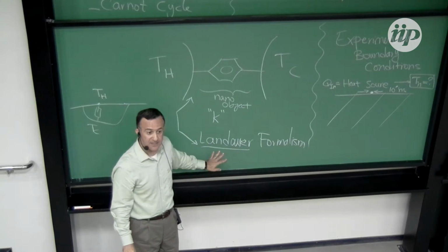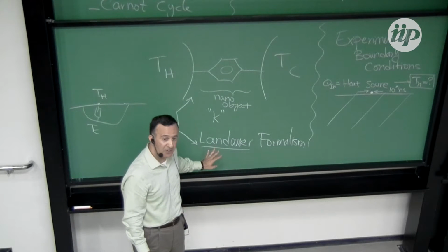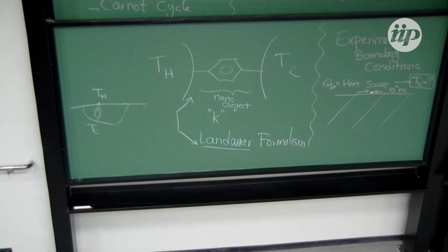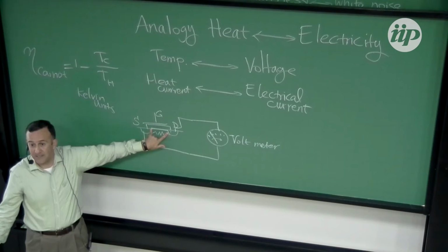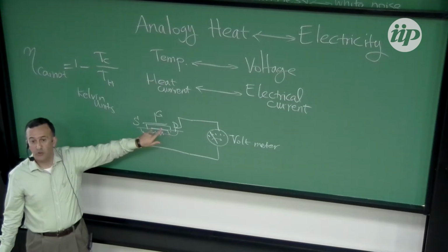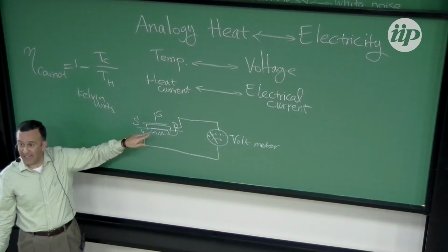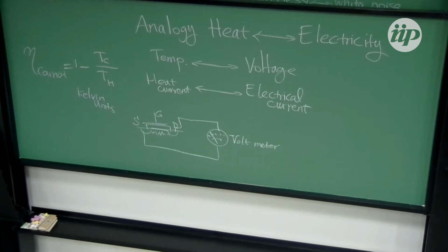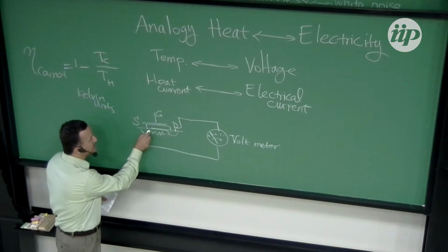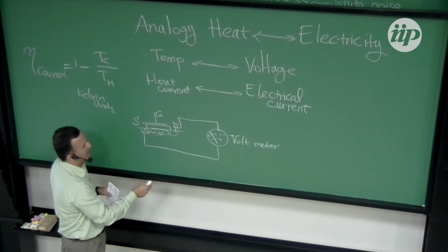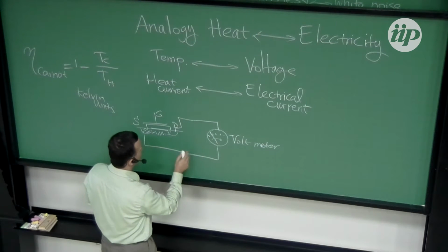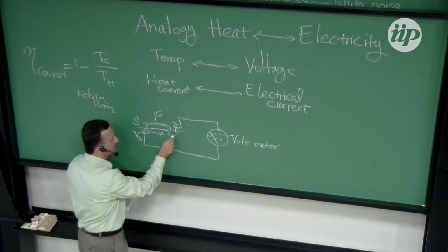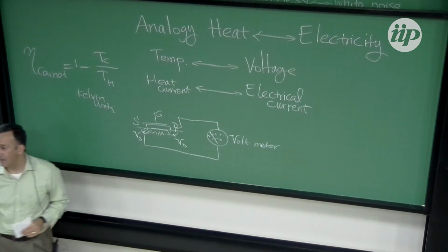But what it is, is a very nice formalism from electrical transport to tell you, in these objects, when I go from length scales of tens of microns, when this is a real resistor and Ohm's law applies, to today's length scale, tens of nanometers, where Ohm's law does not apply, it perfectly explains. Perfectly explains because I can have a reservoir of a high voltage. I mean, I should have put some sort of a voltmeter applied to here and sent the current. But anyway, I can define a voltage at the source. I can define a voltage at the drain without a problem.